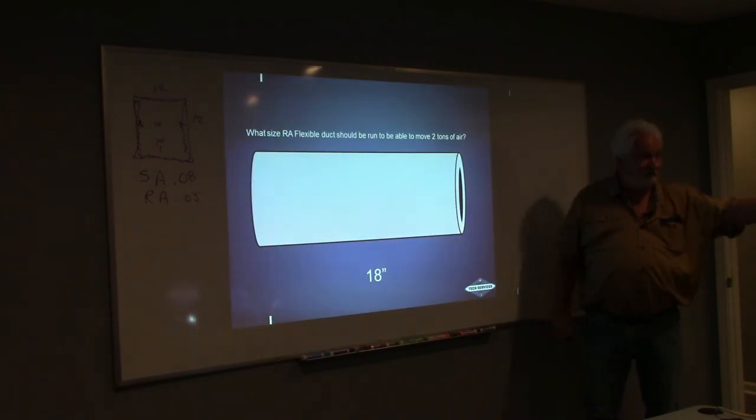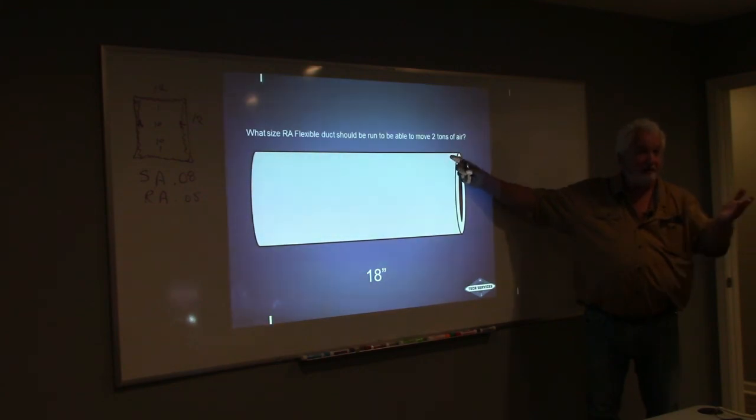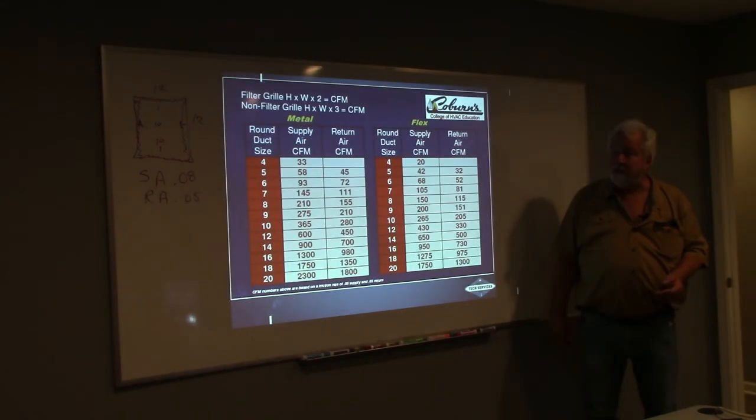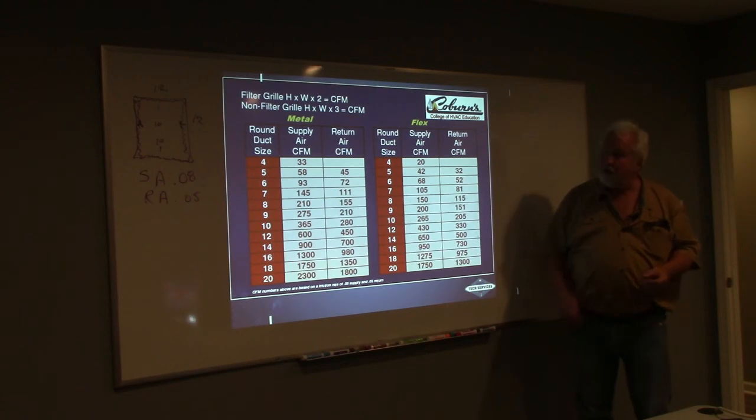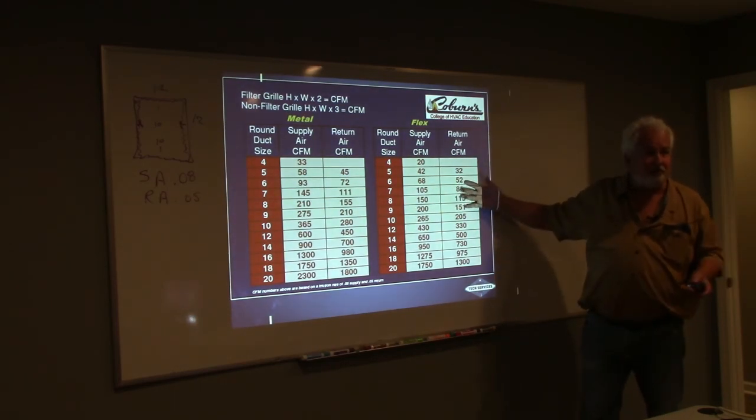But what will it give me? I'll get you that in just a second, because it just so happened I looked at it yesterday with a customer. Good. So the 18 is going to be able to take care of the 800 CFM, right? And we saw that it was a little big too, is that right? Good, because we really needed, what, 17? But we're gonna use 18. With that, we're going to look at a chart that's available. Where do you think this chart's available?